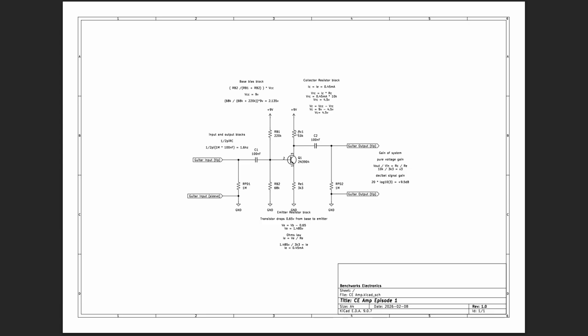So we've got the same pressure and the same amount of water flowing through this section. So that's quite handy because now we can work out what the voltage is here, because we know what the voltage going in is, and we know what the amount of electricity flowing through is, or the pressure at the top here and the amount of water flowing through. So we can do a really simple sum here. To work out the voltage across this resistor, we can take our 0.45 and multiply it by 10,000, which gives us, when we do this math, a value of 4.5 volts.